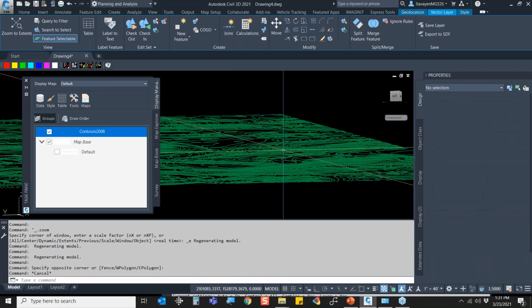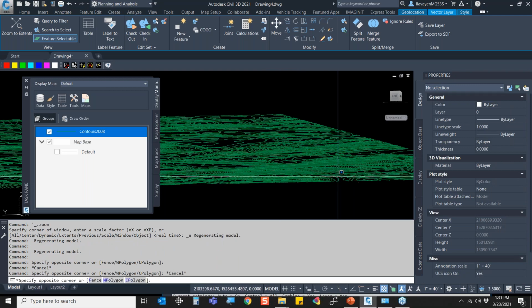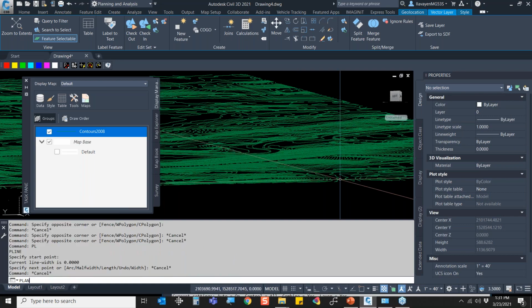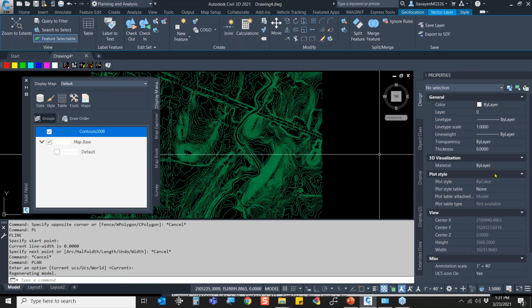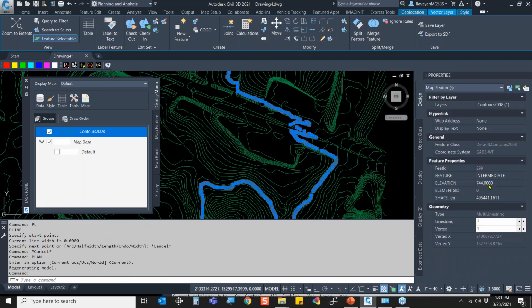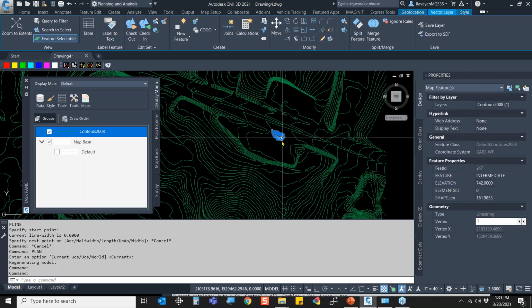And the reason I wanted to take a minute to show this off is that some municipalities give the elevation a slightly different name. They call it Z or EL or ELEV, or someone who may not have taken enough time, it's just called line item 1, 2, 3, 4, 5. That's what's important here, that elevation, because I want to generate a terrain from it.